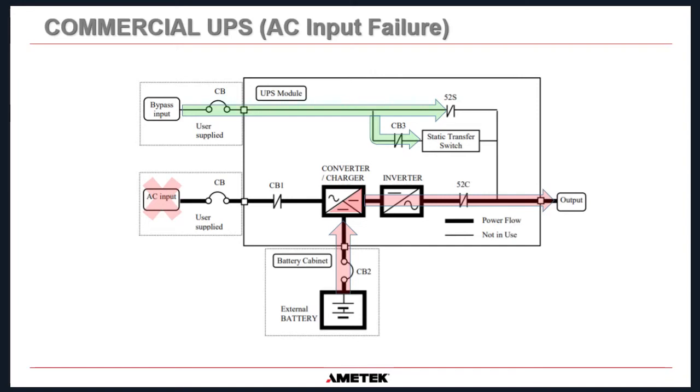And in truth, there is no switching involved here. A lot of people say, oh, it's switched to battery. And that's not the case. It doesn't switch to battery. The charger and the battery are connected in parallel. So if the charger disappears, the DC from the battery is just there. It's just like unplugging the power from your laptop. There's no switching that goes on inside your laptop. The battery just takes over immediately. And that's exactly what happens in a UPS as well.